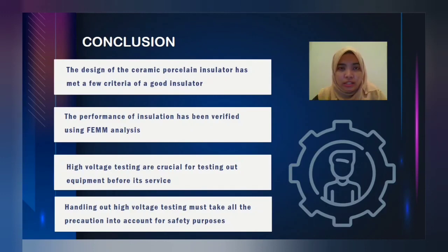during the dry condition there is less humidity, and dirt particles might surround the insulator and produce a pollution layer. The pollution layer will create leakage current and also give rise to flashover and a power outage. This is why the insulator works better under the wet condition compared to the dry condition.